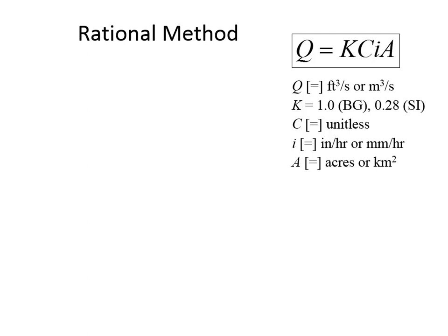So we were talking about a concrete pad that's 0.1 acres. Let's say that concrete pad has a runoff coefficient of 0.95. So what I was saying is the units are a little bit serendipitous. We have inches per hour times acres, and this runoff coefficient is unitless, and what we're going to get is CFS. That will be the runoff in CFS, and so that's 0.6 and then times 0.95, so it's going to be about 0.58 or so CFS as the runoff from that concrete pad.